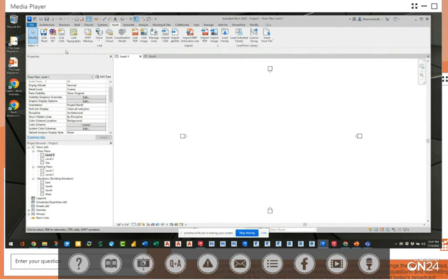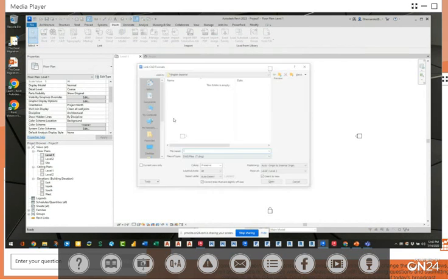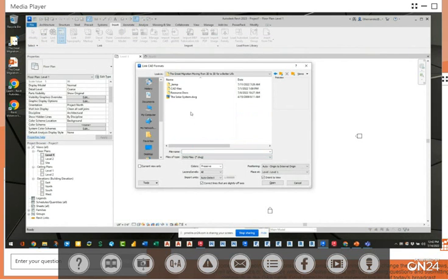All right. So what I'm going to do now is start a project here by going to the Insert tab, because I want to bring something in. I want to link in or XREF in something, and I can link in a Revit project. I can link in a CAD background. So I want to take advantage of my 2D information. So I'll go here to my CAD files, and I'll say, here's my architectural background here, and I'll bring it